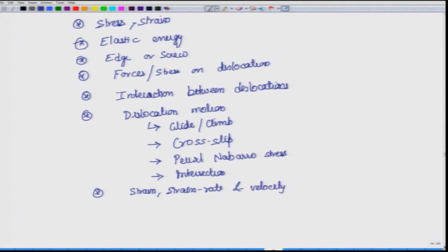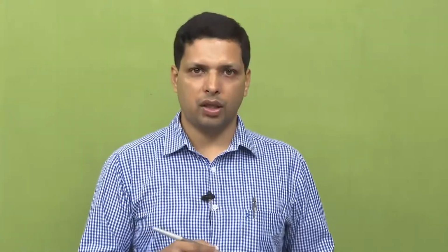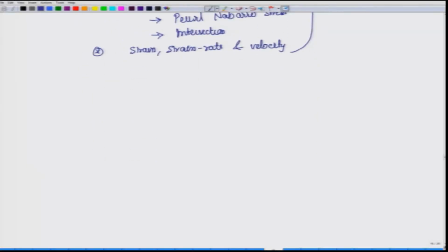of dislocations. So, having looked at all of this, we are now in a position, at least at the fundamental level without talking about a specific system, which will come as the next stage, to say how the dislocations would react in the presence of others or because of the presence of other stresses, and because of that, will they move, how much they will move, what will be the final configuration, where will be the zero energy configuration. And this study is called dislocation dynamics.